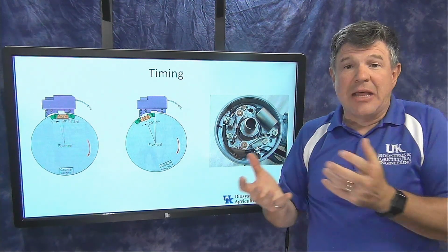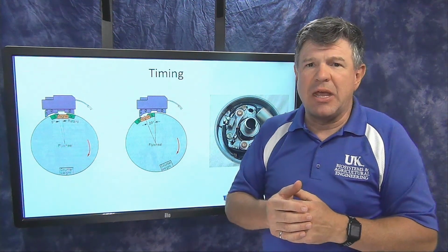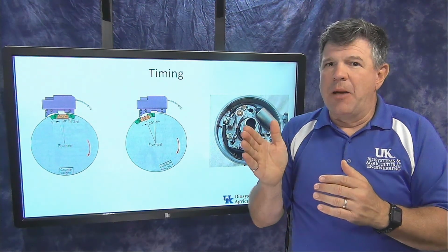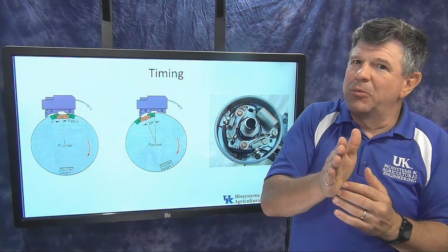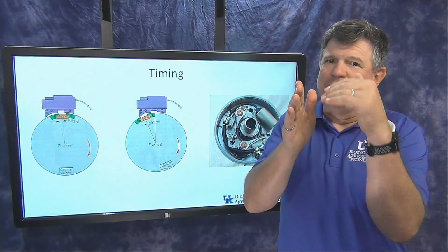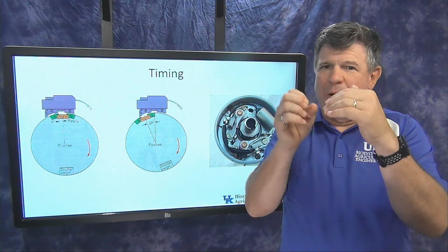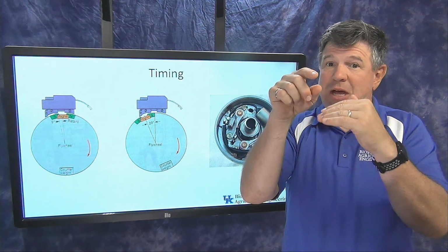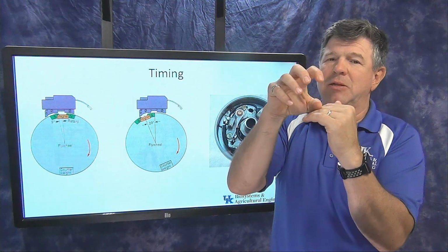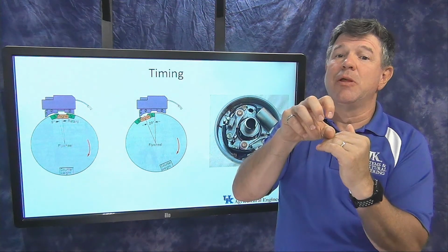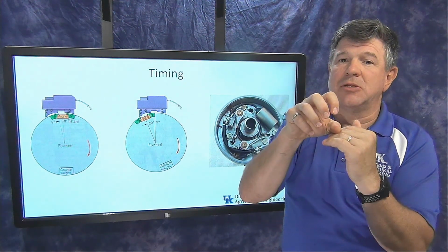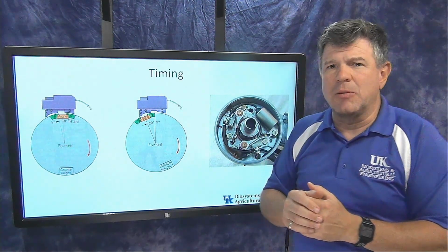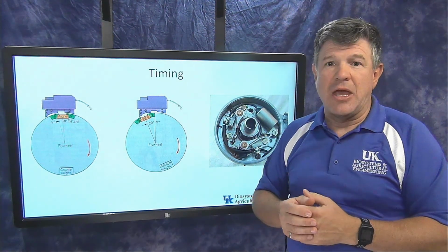Actually, that timing will change based on the speed of the engine. The faster the engine is moving, I may want that timing to be a little bit in front. If you're thinking about degrees of rotation, I want that spark to happen a little bit earlier because, again, it takes time for that fuel to start to burn. I want the pressure to be up and really pushing on that piston when it starts back down. So I may change that timing a little bit depending on how fast the engine is running.